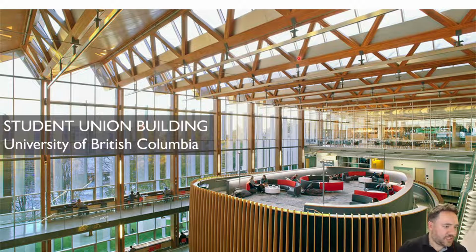Here you can see some nice timber trusses. There's a lot of examples of nice timber trusses, which always tend to look better than steel trusses just because of the material, but a nice combination. These have hidden connections inside, so the steel is actually a knife plate connection.